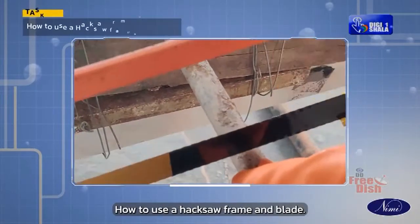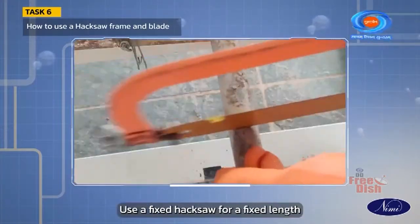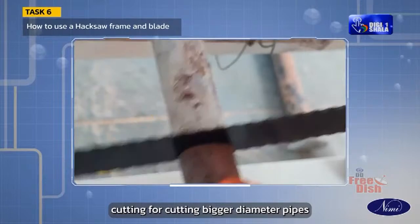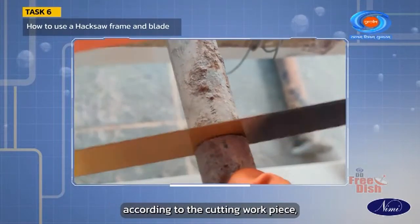How to use a hacksaw frame and blade. Use a hacksaw for cutting flats and pipes. Use a fixed hacksaw for a fixed length and an adjustable hacksaw for different lengths. Use deep cutting for cutting bigger diameter pipes and tubes. Select the correct pitch blades according to the cutting workpiece.